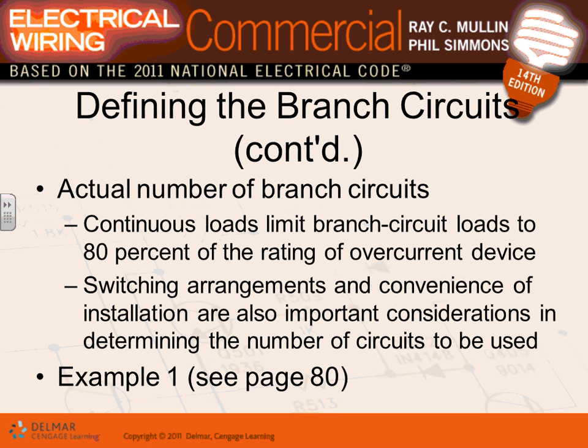Now I can't emphasize enough, if it's continuous load, you're always limited on the branch circuits to what? 20 amps. You're always limited to 20 amps. Here's what I tell you guys, for convenience, different arrangements can happen. For example, parking lot lights, you don't want to mix them with the indoor lights. Can you mix them based on the code? Yes. Should you mix them? No, not a good idea. If I have a parking lot, it's a good idea to group them in 1 or 2 circuits and put them together. Outside lights on the perimeter of the building, I could easily pull them with the interior lights.